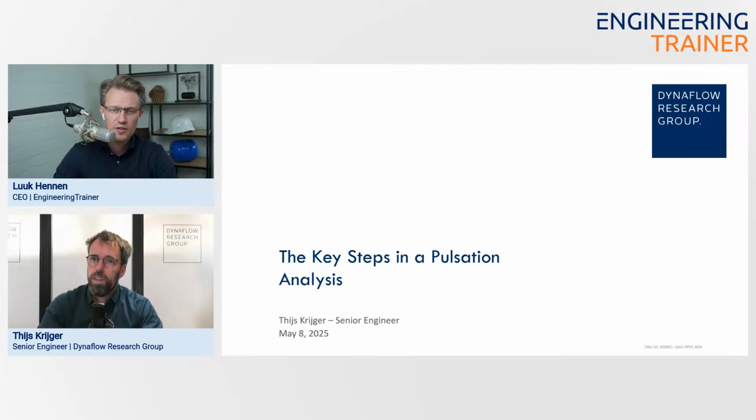So there are guidelines in API standards that can be used to determine what level of analysis would be required. For the larger systems, with more power and higher pressures, a more detailed analysis is required than at the lower power end.